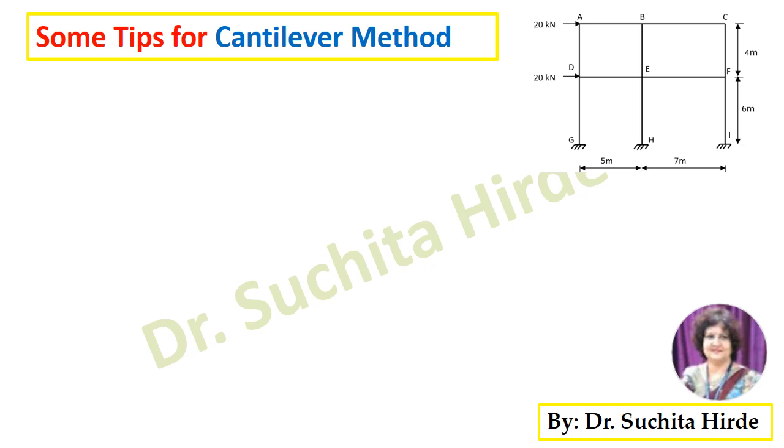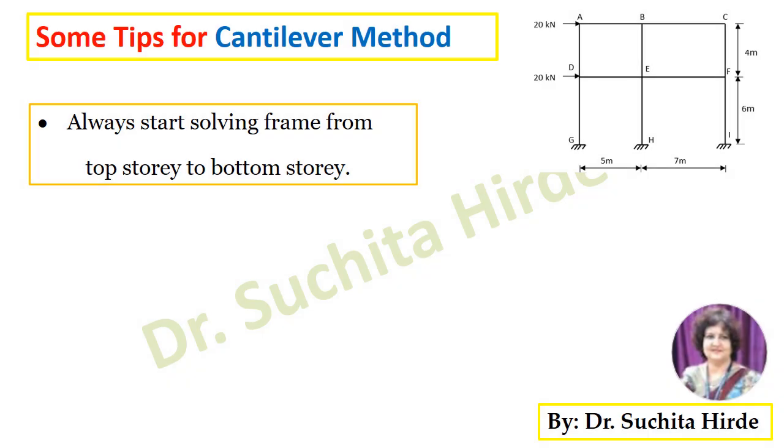Some tips for analyzing any multi-story frames using cantilever method. Always start solving the frame from top story to bottom story.